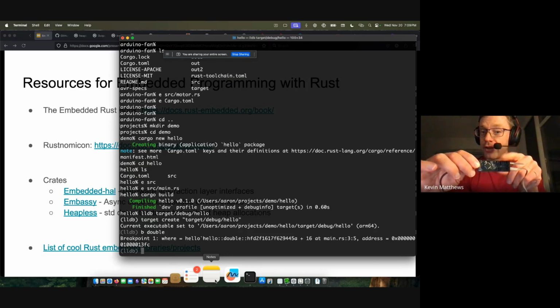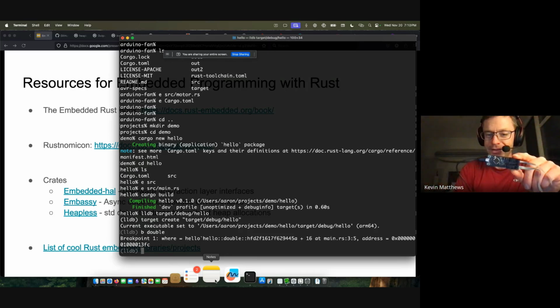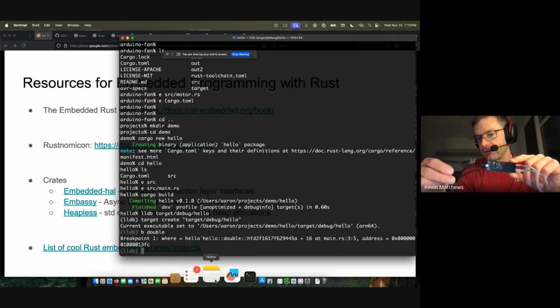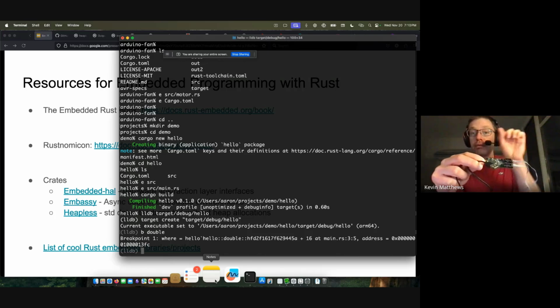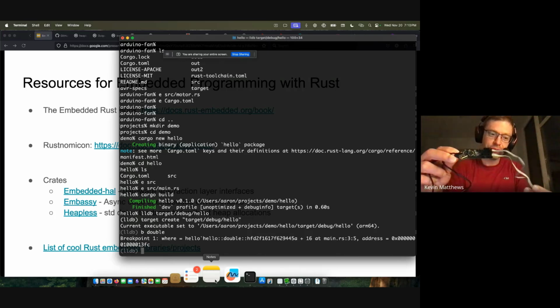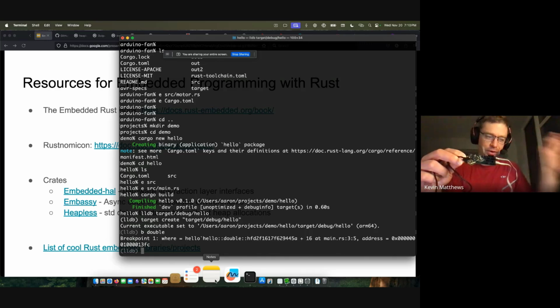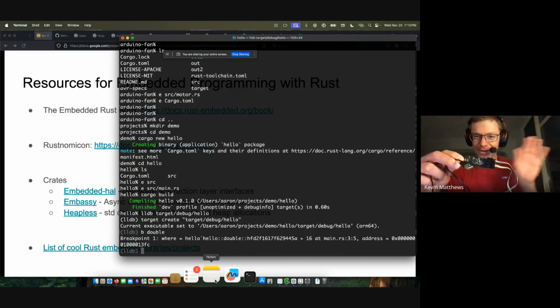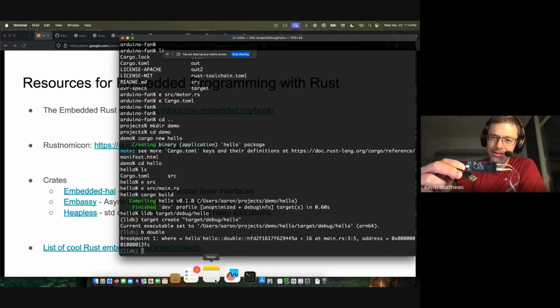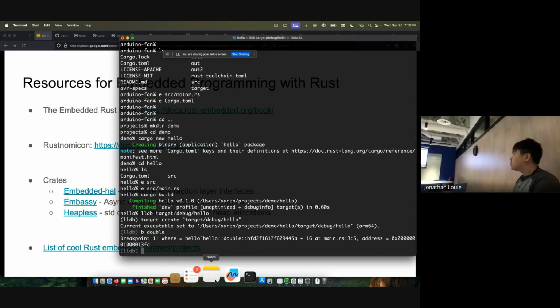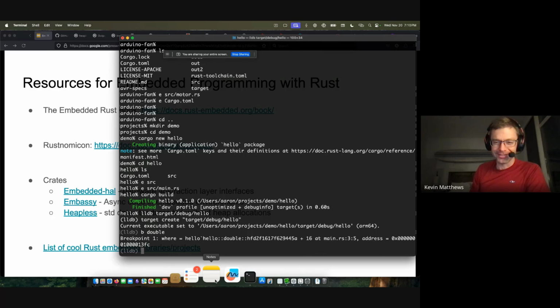So if you plug this into the AVR chip, you would have a bad time. But with this one, you can often run an OpenOCD instance on your chip, and then connect GDB through OpenOCD through this to whatever your hardware is. And then hopefully the hardware on that side is connected correctly. It'll have been wired up that way. Yeah, that's cool. So it's way easier to just have it all running on the host. But if you're doing embedded and you're not running on the host, then you need some sort of bridge. Yeah.